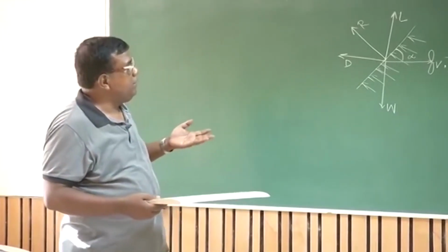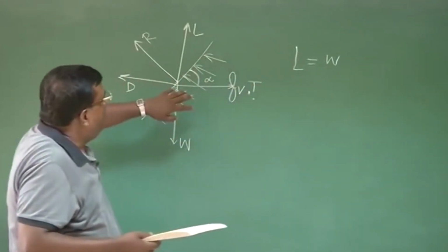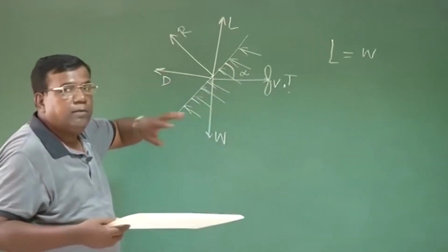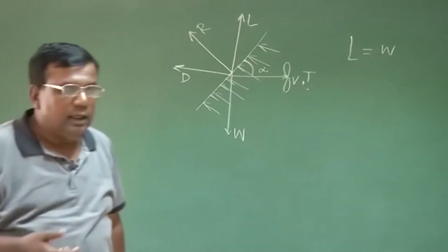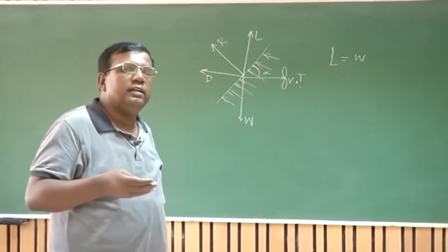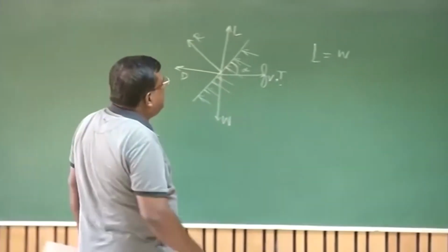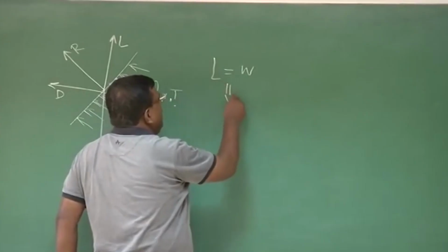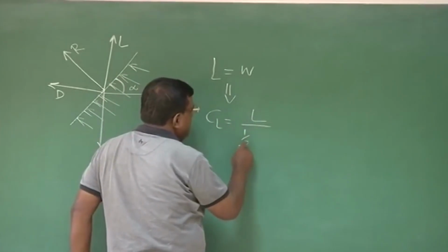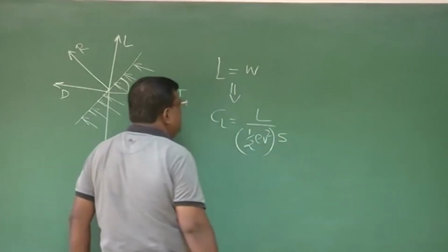And before we go for aspect ratio, we will have a relook here and try to see how I translate this to a pilot in terms of flying the machine. Because I always said, whatever aerodynamics, whatever flight mechanics we do, finally I have to translate this in terms of a language which a pilot can understand. Right? Then from here we realize that we will be operating in terms of CL, which is nothing but lift non-dimensionalized by dynamic pressure times S reference.